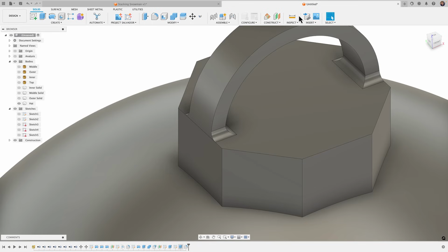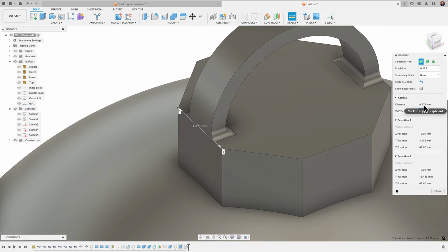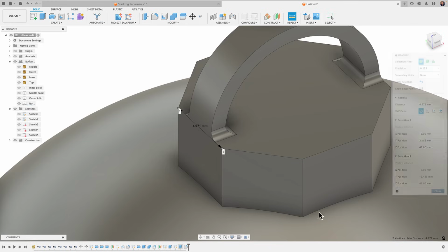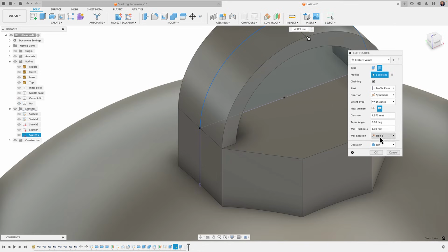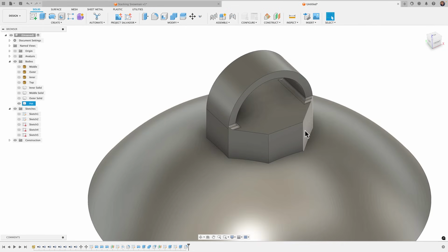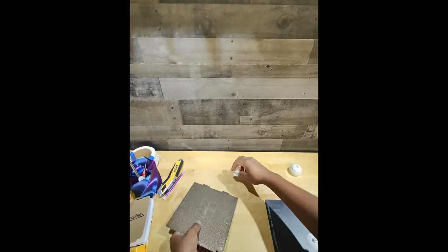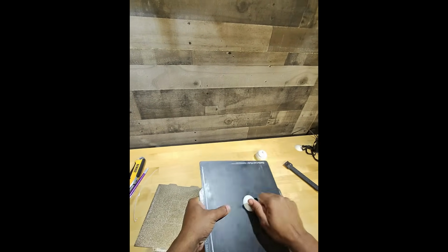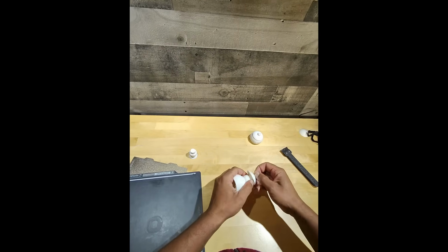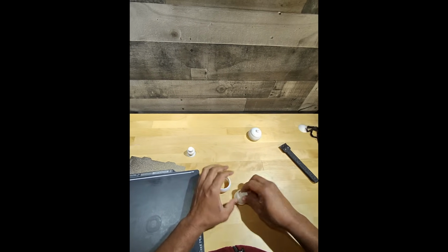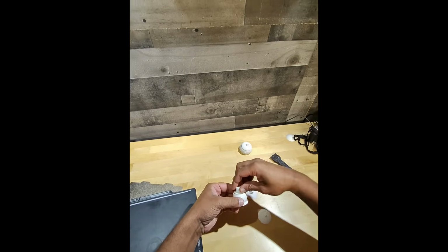Let's grab that distance, we'll inspect from that point to this point here. Distance 4.9. I'm going to click there to copy it, and then we'll go back to that extrusion. Just paste that there. There we have it. We're good. That's much better. All right, got the modified snowman head and the cover for the top here that I fixed. So, okay, here what we're going to do is let's take this off. Substitute this head here for this head, and let's see how that fits.